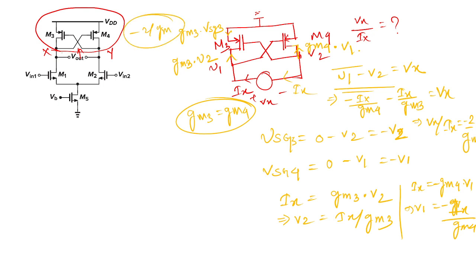So we can represent this structure as two series resistances, minus 1/gm and minus 1/gm. Then you can draw an axis of symmetry, and the final one-sided circuit will be like this: M1 with minus 1/gm as the load.